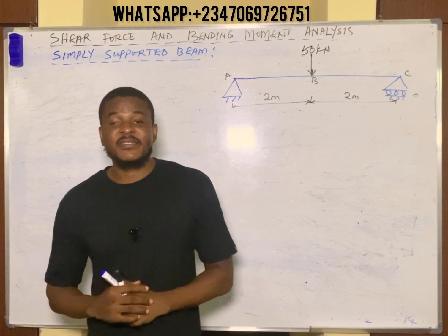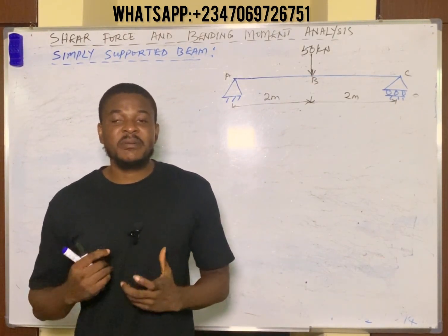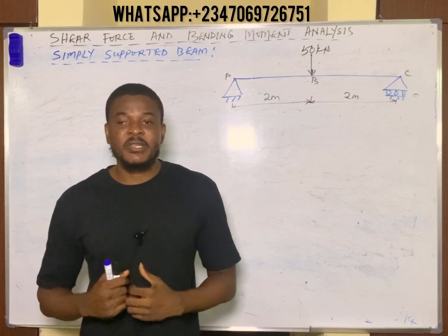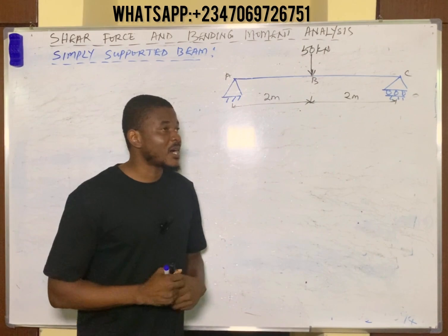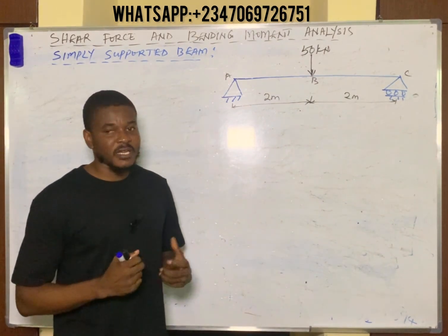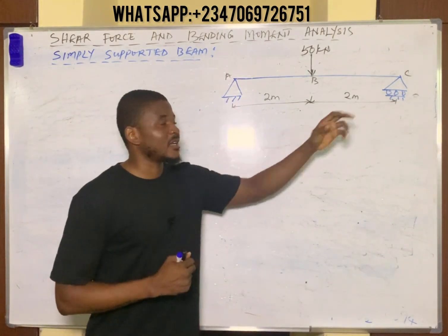to Engineers Mindset. So in this video, we are going to be looking at how to draw the shear force and bending moment diagrams for a simply supported beam carrying a point load. So we are given this beam on the board and we are asked to draw the shear force and bending moment diagram. Our first task will be to find the support reactions at A and at point C.